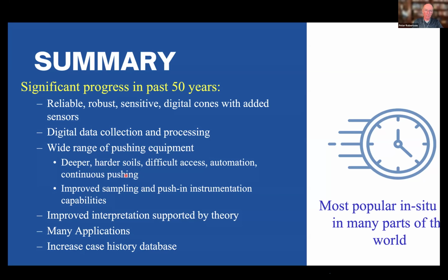I was at a site just 2 weeks ago, in an area with residual soils. They were using a large dozer, and they had attached a portable CPT hydraulic unit to the back of the dozer. They were pushing into fairly stiff residual soils, and pushing over 30 meters with a 20-ton reaction from the dozer. Improved interpretation supported by theory, many applications, and an increased case history database, lots of case histories.